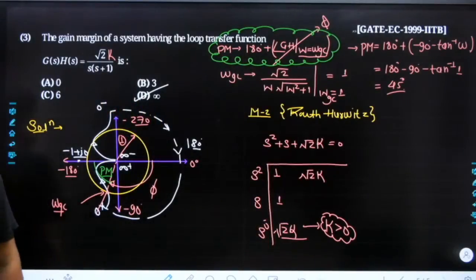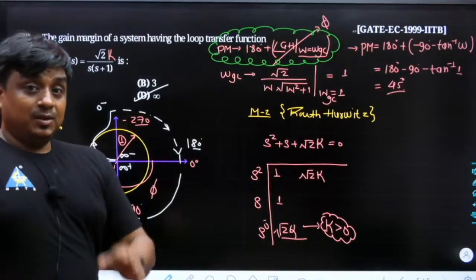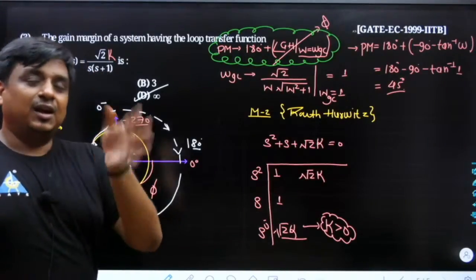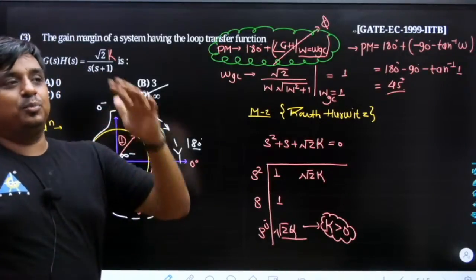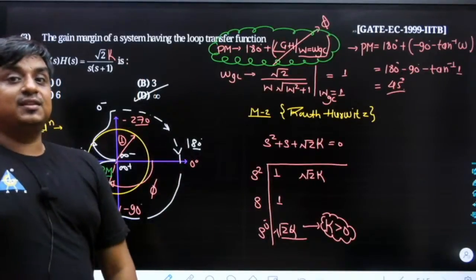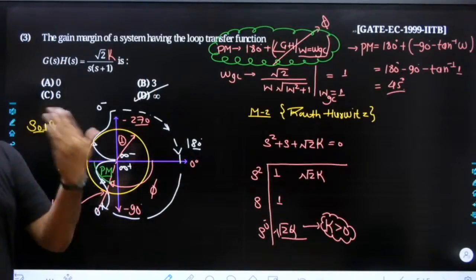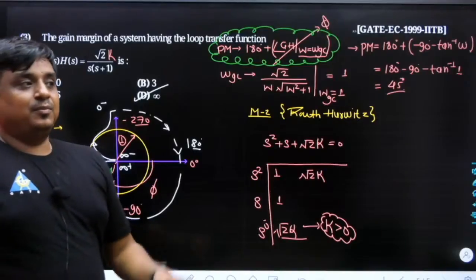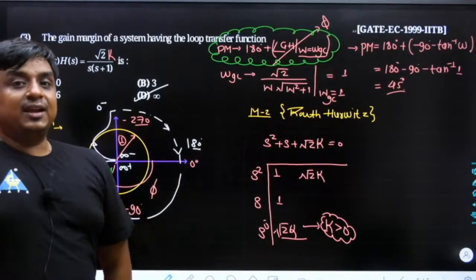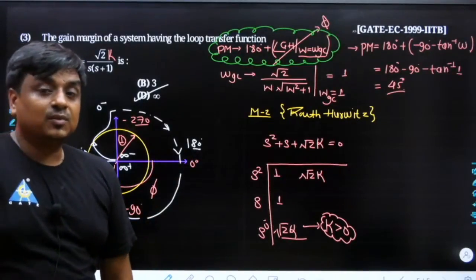Obviously, sir, 1 divided by S plus 2 is going to be the more stable system, because anyhow I can keep putting in higher values of gain, and still the system does not go into the zone of instability, and at the same time I can keep pushing lag into the system and it does not go into the instability region.